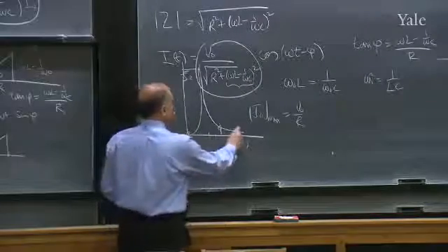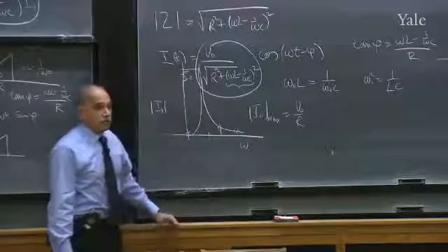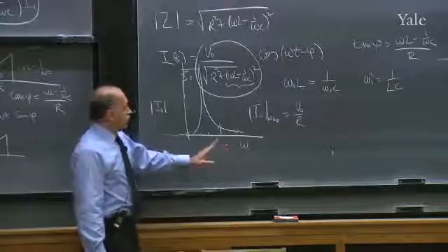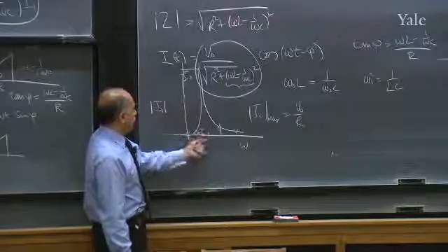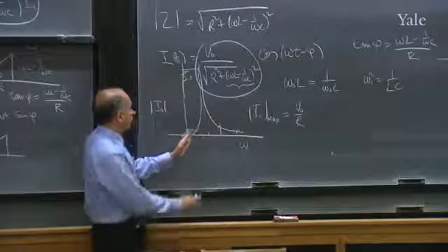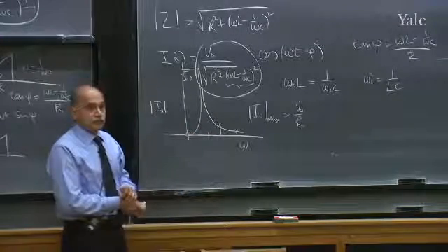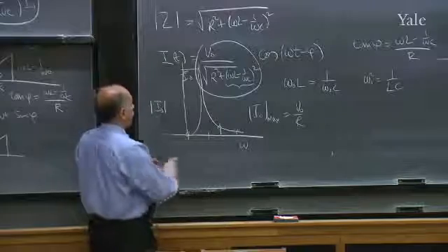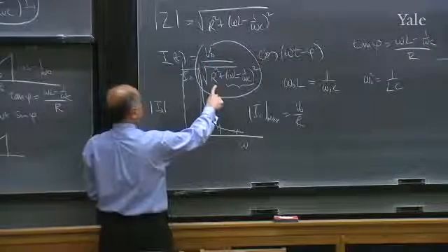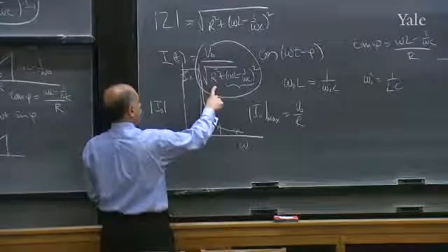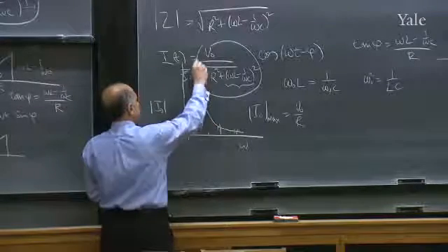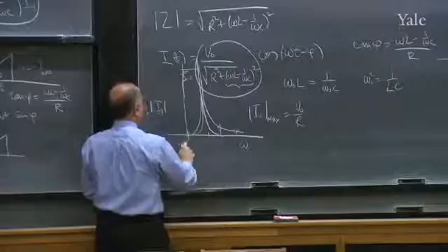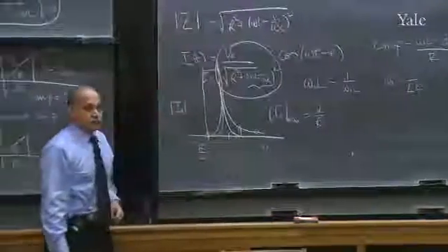And there may be yet another station you can hear in the background, because if you don't want to hear them, you would like to get 0 signal from them, but you cannot kill this function except at one frequency. But you can make it very sharp. If R is very, very small, this function will be very large at resonance, because B naught over R will be a huge number. It'll also be very narrow. So you can make this thing very sharp. And that's really controlled by the ratio of R to L.